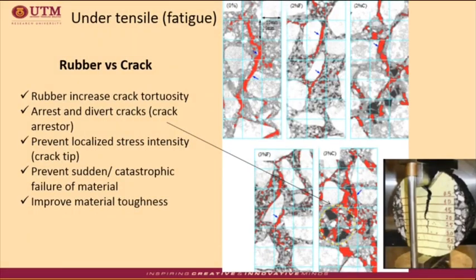In this slide, all the specimens show a large number of cracks present in the interfacial transition zone around the larger aggregate particles and mastic. This is believed to have been caused by insufficient bonding between the aggregates and the mastic.